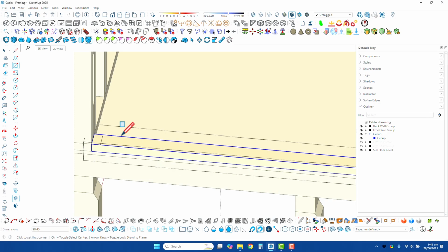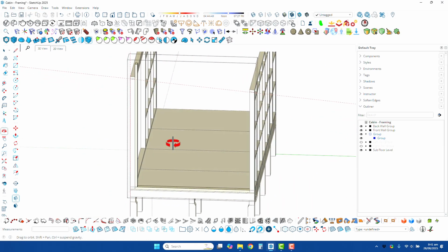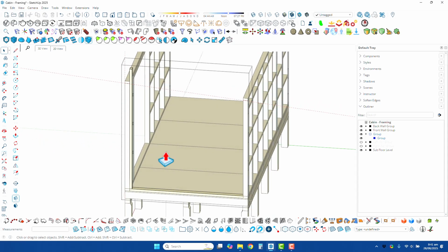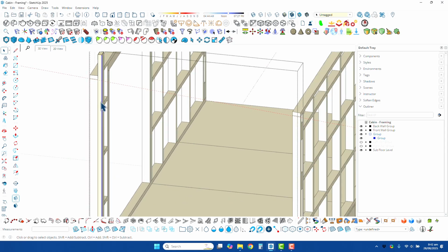That's better. Select our push pull tool and we'll extrude this on the blue axis 2500, and that should go right past the guidelines. I hope it does. Cool. Now what you'll see is the dotted line has grown, so we're still working inside of the group, but this again is just faces and lines, and we want to keep it like that.